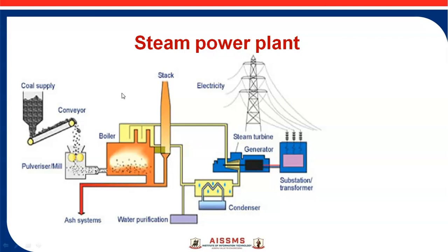Generally, the function of the boiler first. The boiler consists of the boiler shell, which is a water tube type of boiler, and a superheater is there. The feed water supplied from the economizer is first converted into wet steam, and this becomes superheated steam because of the heat supplied by the hot flue gas, and steam is generated at high pressure from the boiler end.